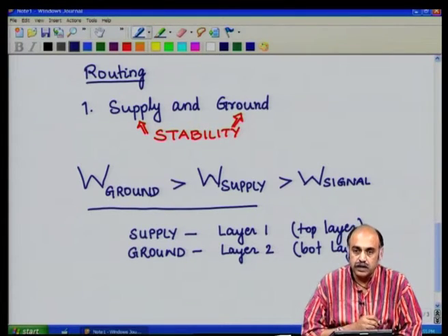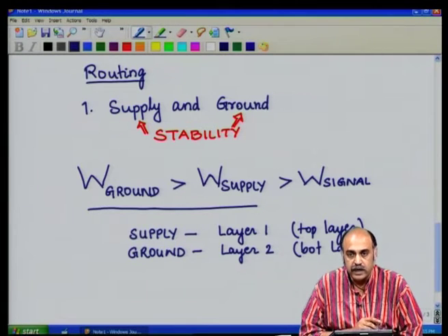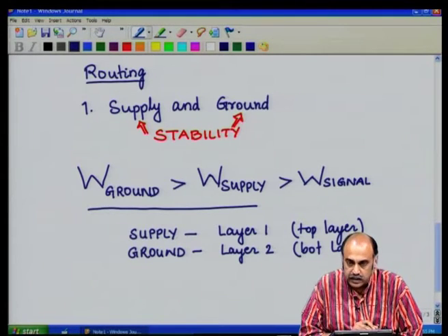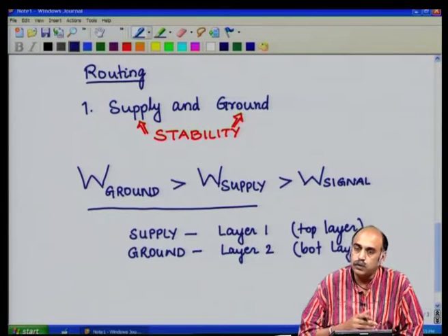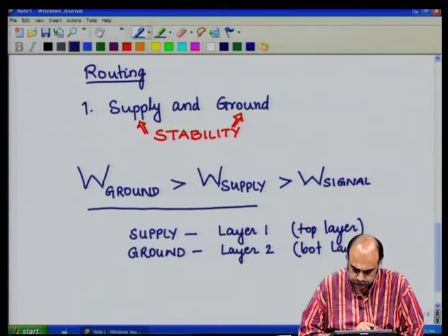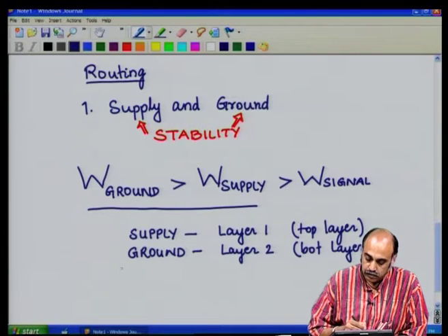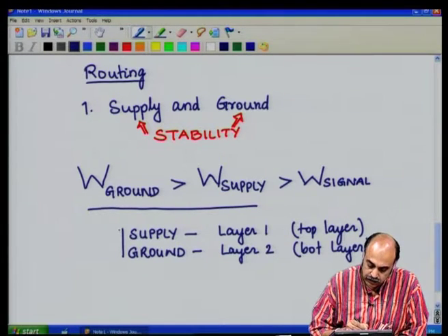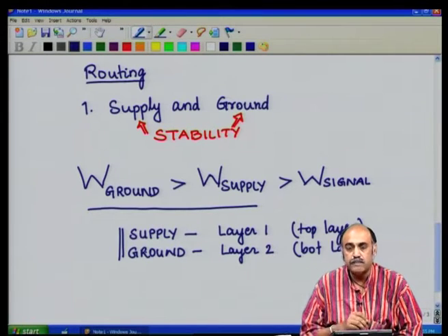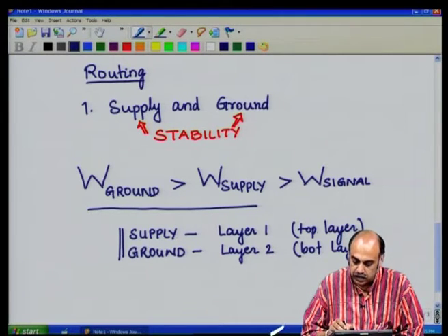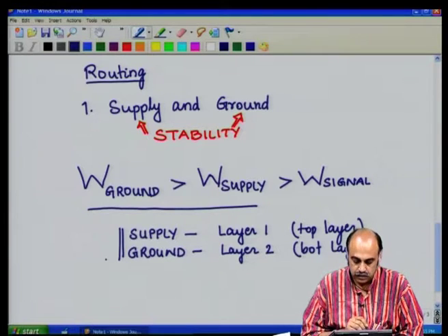If it is a four sided board, then you can dedicate one intermediate layer for ground, one layer for supply and two layers for the signals. But in a two sided board, it is very difficult to stick to this rule, however the majority of the tracks can be made to adhere to this rule.